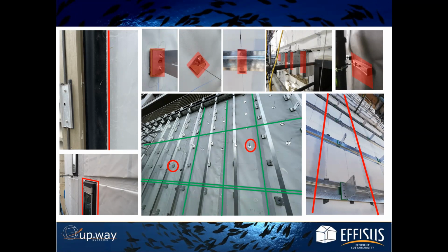These are very weak spots on a facade, as is very easy to understand, because imagine that you create one perforation on your wall and you do not seal it properly. Imagine the nightmare that you will have on your project when you find out in the future that there is water going inside your wall and you cannot find where it is located. By doing these details, by doing site training and talking to the teams that are applying the products, we are mitigating many future errors and mistakes at site.